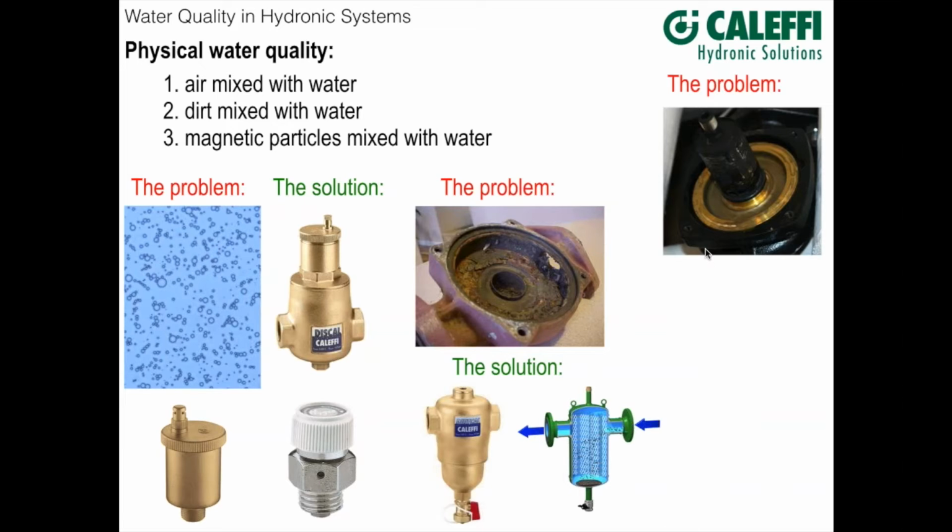Anytime you have a system that has cast iron in it, steel pipe, cast iron boilers, or steel buffer tanks, for example, there's the potential to get iron oxides. This is especially true if you have tubing in the system that doesn't have a good oxygen barrier, or even with an oxygen barrier PEX tubing, if that system is operating at high water temperatures, the effectiveness of that oxygen barrier does decrease.